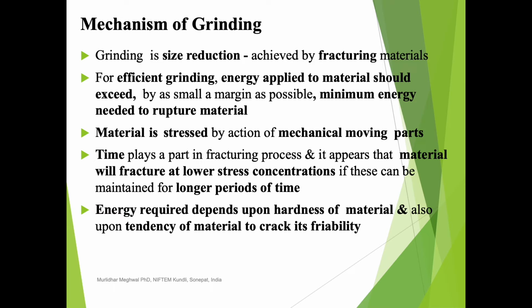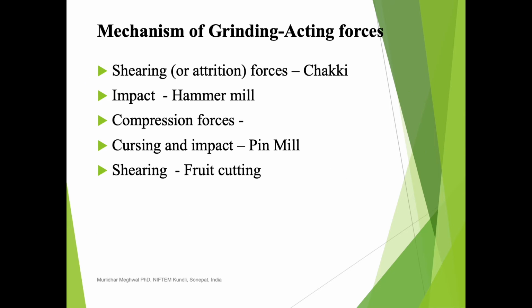So when we apply the energy, there is stress action by the mechanical moving parts of the grinder. Here time plays an important role in the fracturing process. It appears that a material will fracture at lower stress concentration if this can be maintained for a longer period of time. Energy required depends upon the hardness of the material and also upon the tendency of the material to crack, its friability.